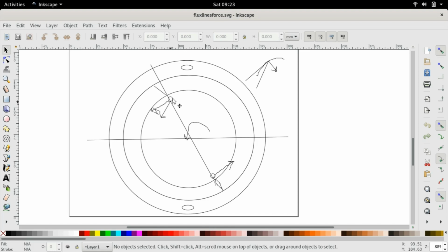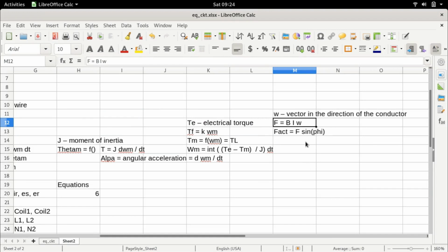So in this simplified case, remember, this is a simplified case, we are considering all the rotor bars concentrated on just these two slots, right? In that case, since we have two mechanical forces, one at the top and one at the bottom, and they are both producing a force which can rotate it in the same direction, then the total torque is the sum of these two. And if we say that these two are identical, and you can pretty much assume them to be identical, then it's simply twice force multiplied by R. So I can write that as well. Let me just extend it.